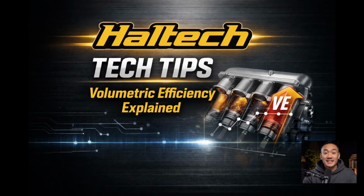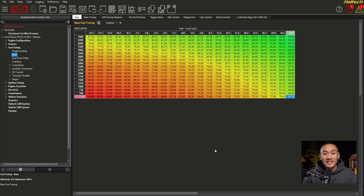My name's Chris, and in today's video, we're going to walk through the VE airflow strategy in Haltech NSP, focusing on what VE actually represents, how the ECU uses it to calculate airflow, and how to sanity check your numbers so you know your tune actually makes sense. We'll look at where the VE model lives inside Haltech, break down the math that happens in the background, and show how to validate VE values at idle and wide open throttle.